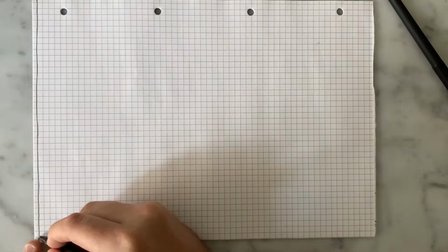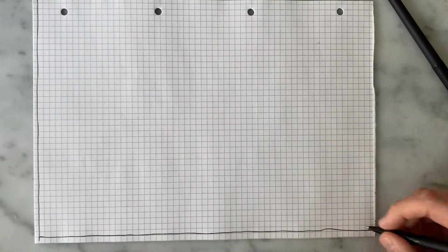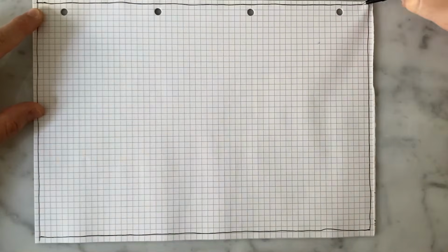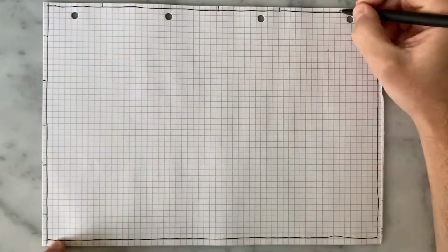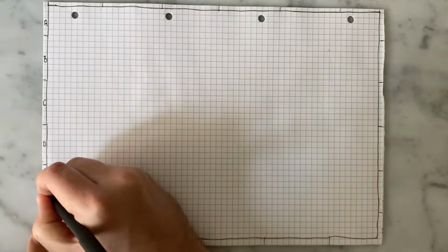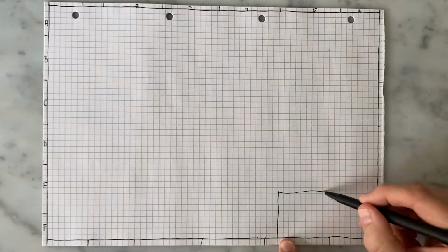If you are drawing a process and instrumentation diagram from scratch, start with a grid coordinate system. All P&IDs that I've ever worked with have this, even though I don't think I've ever used it. There's always letters on the one side, numbers on the other, so that you can refer to grid coordinates if you ever want to, I don't know, refer to the location of a specific instrument on this drawing.